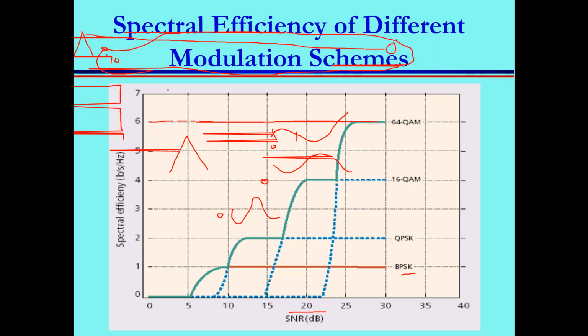Is this the only solution, adaptive modulation? No, of course, we also have adaptive power allocation. Instead of changing your modulation, you can change your power. For example, when the user is here, I don't need too much signal to noise ratio. I can transmit with low power, but when the user is very far, you need to increase the power. Also, you can use both power and modulation, adaptive power and adaptive modulation, to adjust based on the channel conditions and application requirements.